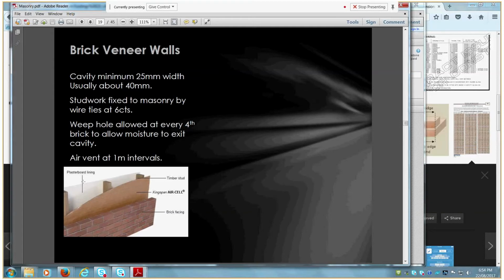So your cladding would have to be something different. Yes, so we can't use plasterboard on the outside, but we could use, for example, fibre cement sheet or pretty much any of those, or weatherboard, foam cladding with render. We could use Hebel if we wanted, thatch or straw bale, hempcrete. Well, actually, no, you probably wouldn't use hempcrete on the outside. You're getting very heavy. But yes, or custom orb or corrugated steel sheeting on the outside.